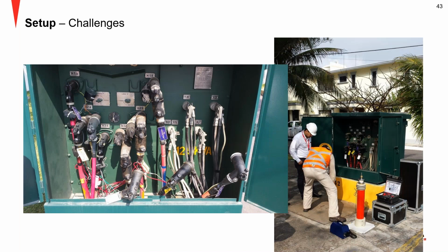And then here, obviously, you also have challenges in the field, right? Everybody knows this. I mean, I've seen similar pictures in the US as well. So sometimes it's not so easy, but you can make this work by using a proper T-body there, or an elbow connector, and to have a low corona, a low PD connection there as well. It's definitely doable. It might not be perfect in every case, but there are ways of getting it done.